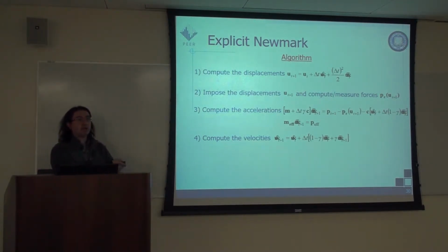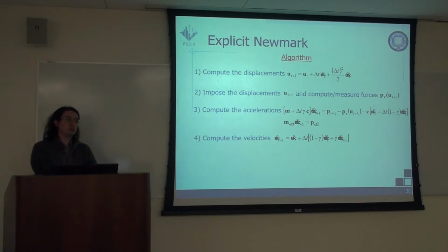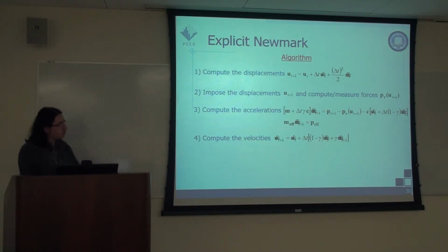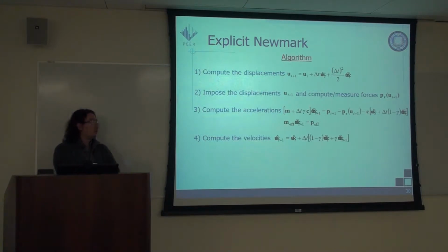On the analytical side, we get the resisting forces from the constitutive relations, and then eventually we obtain the resisting force vector. This resisting force vector and other terms are used to compute accelerations, and then eventually you compute the velocities, which completes the integration time step, and we are ready to move on with the next.